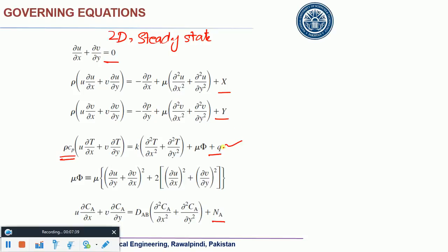Is there any kind of source term? Not at all. So let's disregard this. Let's talk about this term, U partial T by partial X. Now U is significant. What about partial T by partial X? Why? Because we are talking about isothermal plates. You remember, we are talking about this arrangement where X is the horizontal axis. If this whole plate is isothermal, it means this plate is getting a temperature of T1 and this plate is getting a temperature of T2.